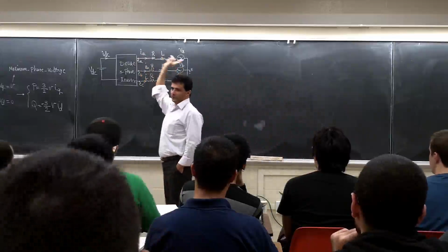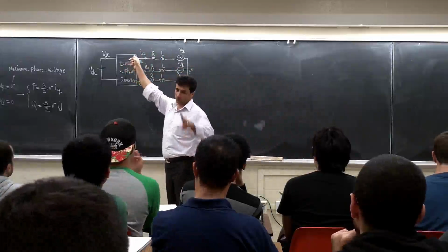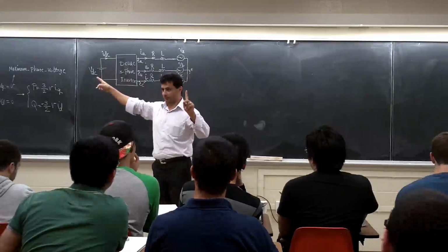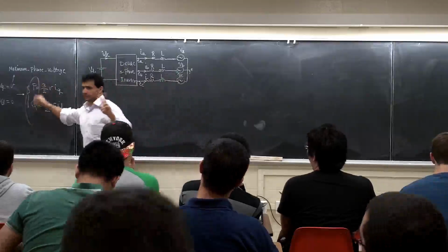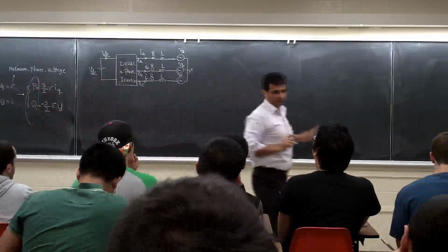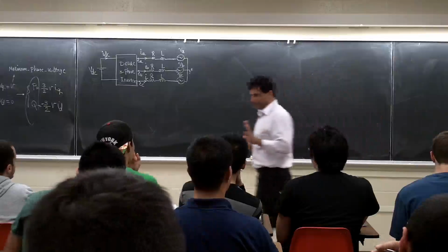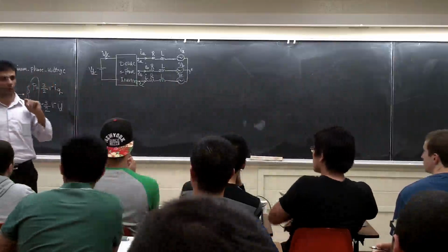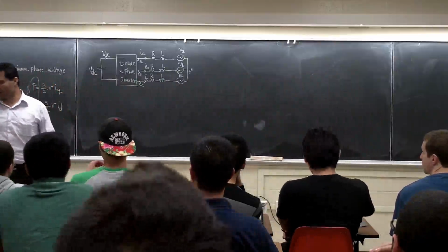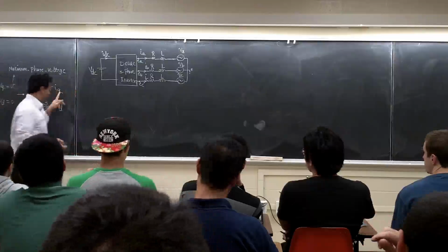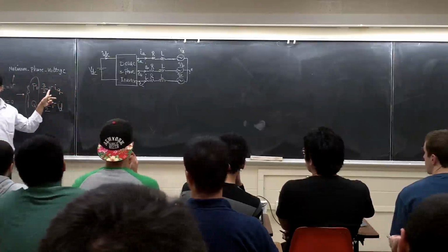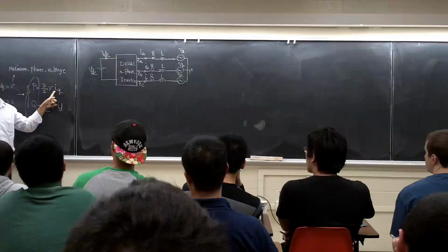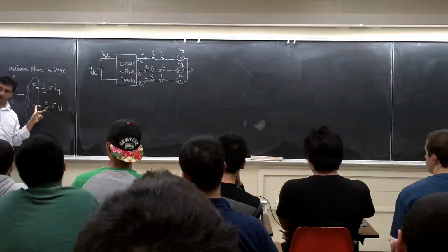You want to control the power going this way or that way, right? But you want to control both of them, P and Q, right? You have an active power and reactive power. You want to control both of these. For example, I want to charge my battery with 2 kilowatts. I want to charge my battery with 5 kilowatts, right? So this is what I want to be able to control, to say, hey, go with this much power charging. Go with this much current charging. Power and current, they're the same. Why? Because it's a constant number, right? For example, let's say 5 kilowatt means, for example, 10 amps. 10 kilowatt means 20 amps, right? And Q is related to what?